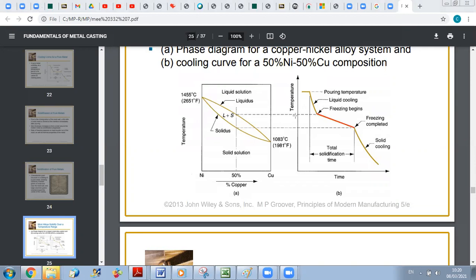So if I am heating, the change from solid to liquid will begin at the lowest melting temperature, and it will end at the highest melting temperature, because you have two components. This is why the melting phase will not be at constant temperature. It will be at variable temperatures. You should just know the behavior of the graph, but we will not go over calculation details, okay? Okay, doctor.